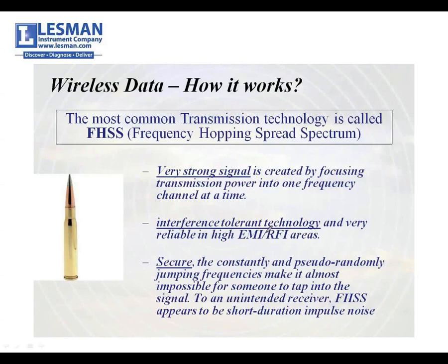As we talked about, there is frequency hopping, FHSS, frequency hopping spread spectrum. You might have heard this on a cordless phone, or you may have heard the term before, but all you need to know is we're hopping at all times so that we're not hogging a channel, so that multiple users can share the airwaves. When we're in the lower range of frequency, the 900 megahertz, we are using this FHSS technology, and I'll show you a slide and a couple more that'll make more sense of this.